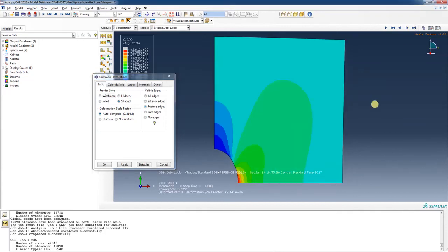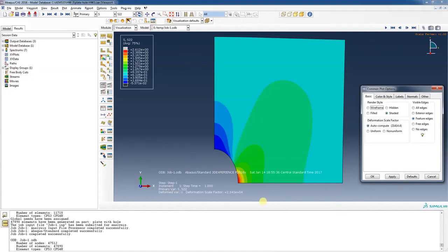I want to point out something else. So right here, the stresses change a whole lot. So we go from this red all the way to the green in the distance of a few millimeters. So it's 2.612 all the way down to maybe about 1.5 megapascals of stress, all in the span of a few millimeters.